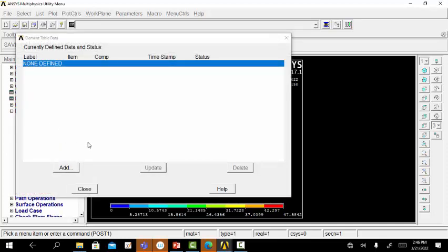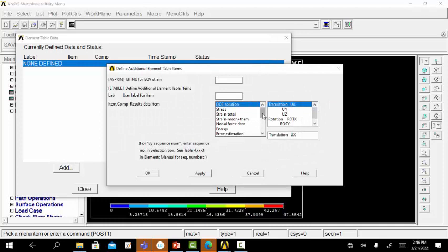To read the stress results, go to element table, define table. With the aid of sequence numbers, we can define the bending stress results on the beam. So add the sequence number for the bending stress value as SMISC 32 for the ith node, and SMISC 37 for the jth node.